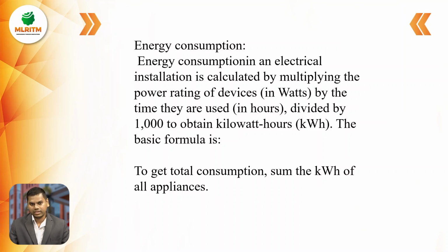What he is saying here is that the energy consumption in an electrical installation is calculated by multiplying the power rating, which is in watts only. The power unit is watts. It is multiplied by the time they are used in hours only, not seconds or minutes. It is divided by 1000 to obtain the kilowatt hours. To get the total consumption, sum the kWh of all appliances.